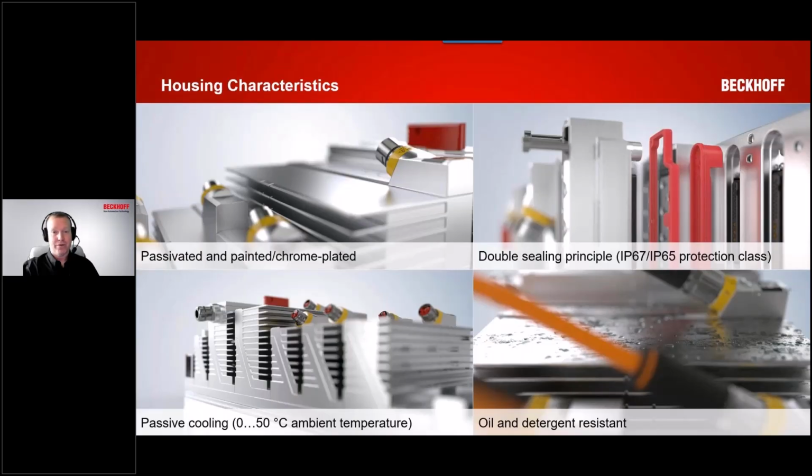Right? We covered both. We did the IP65 test with the jet of water, which is part of that test, and then the IP67 is a submersion test for a period of time. So it is important to understand that that's rated for all of that. It is truly rated to handle these harsher environments. And that's where some of the rest of this comes into play, like the oil and detergent resistant, right? That kind of speaks for itself.